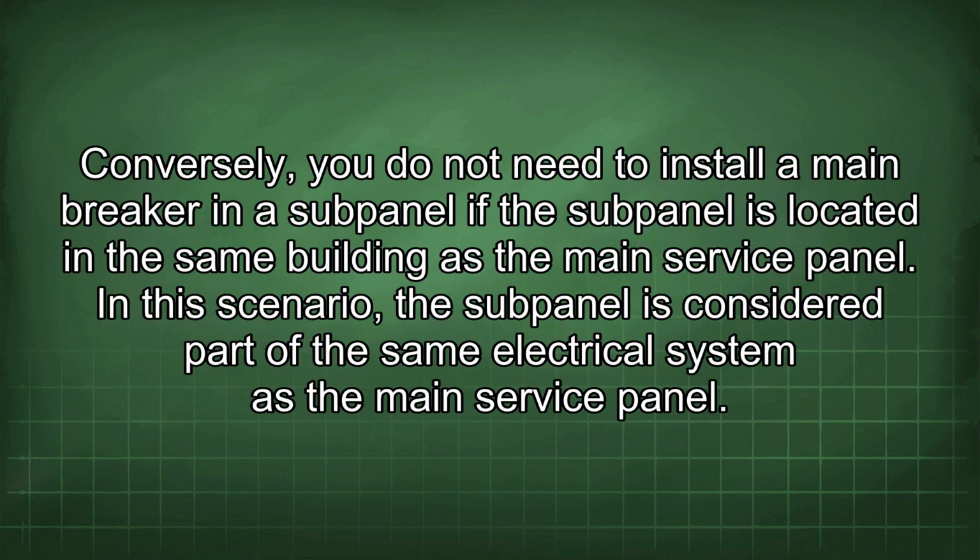Conversely, you do not need to install a main breaker in the subpanel if the subpanel is located in the same building as the main service panel. In this scenario, the subpanel is considered part of the same electrical system as the main service panel.